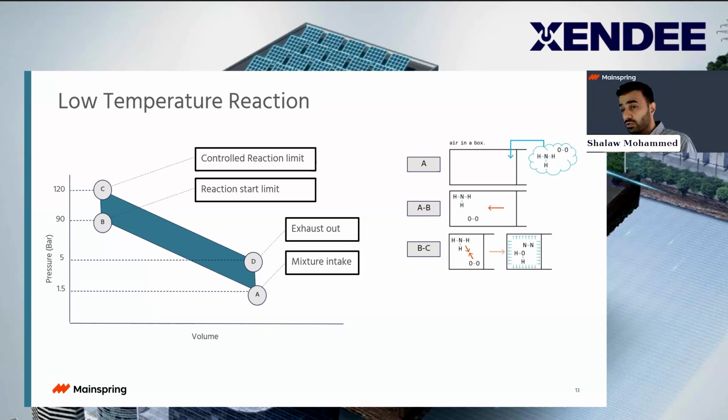And this is a controlled reaction. We know exactly when this reaction happens and we control it. We control temperature and we control pressure inside the cylinder. And this is how we're able to achieve low NOx, because we have a homogeneous, low temperature, flameless reaction. It happens equally all over the place. There's no flame involved and it's homogeneous, so you don't have any hot spots.